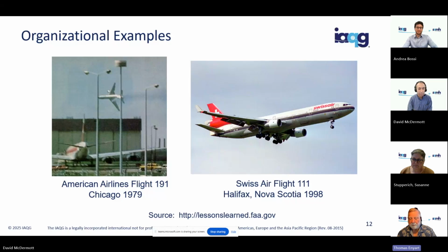First, the in-flight entertainment system wiring was not properly coordinated in the certification process. Second, the maintenance oversight did not detect the faulty wiring. The flight crew was unable to deactivate the in-flight entertainment system electrical supply due to the lack of information. Finally, it was highlighted that there were regulatory oversight and certification gaps. The aircraft's design and the absence of adequate emergency systems to deal with such situations contributed to the fire spread.